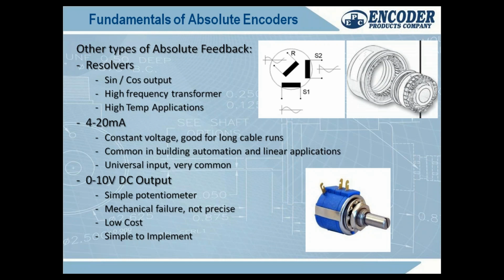So if you have an application where you're looking at getting positioning within a very hot area, resolvers are a great choice for doing that. You'll have to mitigate the noise problems, and they're a little pricier for the receiving electronics to do that, but they're a great alternative for high temp. I had one application that I just pushed a customer to a resolver because it was an oven for a chicken nugget cooking machine, and it was just too hot. And why try to make something fit that doesn't? So that's a great solution for that.